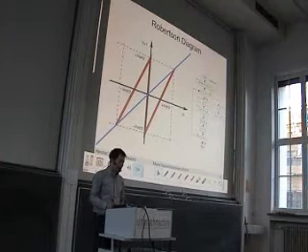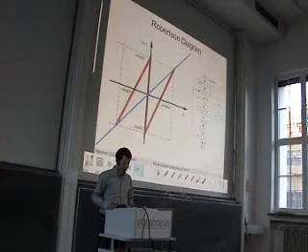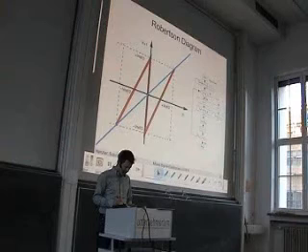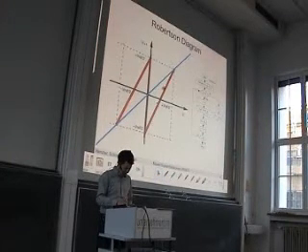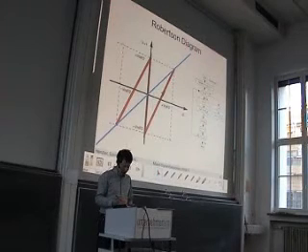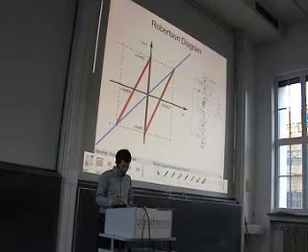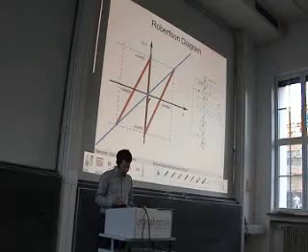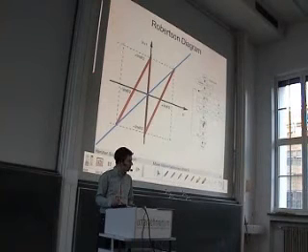We saw that we can plot this algorithm in this diagram to find a graphical solution of this. Therefore we had two lines. The first line here on the right hand side represents exactly the left branch here in the algorithm. So if we are larger than 0, which means that we are somewhere in this interval, then we reduce the internal voltage by Vref over 4 and amplify this by a factor of 2.